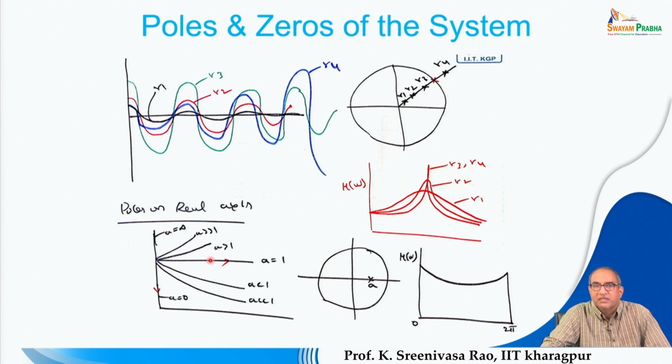Therefore, you can say that here the system is marginally stable. And if the root is outside the unit circle, then it offers a growing exponential, so the system becomes unstable. If the root is at infinity, then it just suddenly shoots up, the system is unstable, and here the damping is very fast, it is a highly over damped system at very higher values.